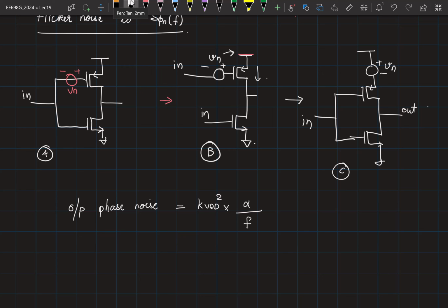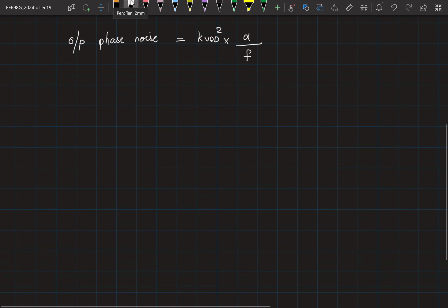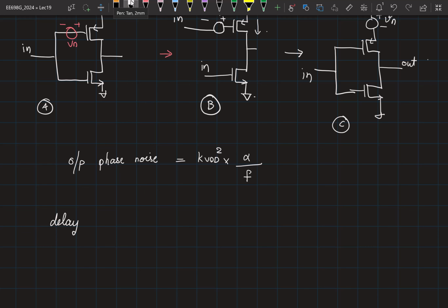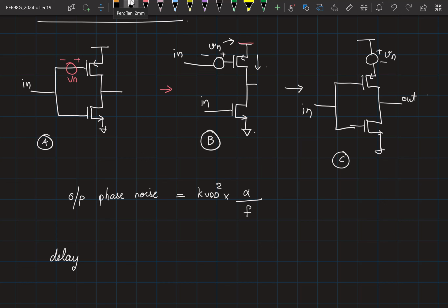Okay, so now we have seen delay line, we have seen a ring oscillator. Let me draw a quick comparison between the two. What to do for the NMOS side, because that one becomes the ground side, right? We cannot use KVDD, or will it be the same? What do you think we should do? Let's say instead of the PMOS flicker noise, I considered the NMOS flicker noise. The same thing will be there, but in place of KVDD square, what? You will have to find the equivalent. Yeah. So if you had a fluctuation in the ground, the output delay is going to get changed, right? So you find out what is that relationship. Basically, you plot delay versus the ground voltage, find out the slope of that at ground equal to 0. So that slope square into the flicker noise of the NMOS will give you the PSD. Is that clear? Is that okay?